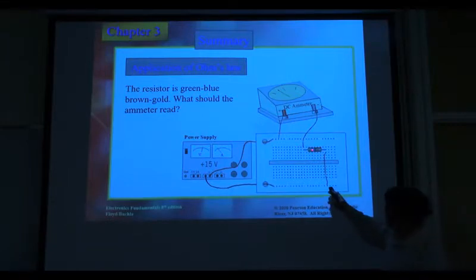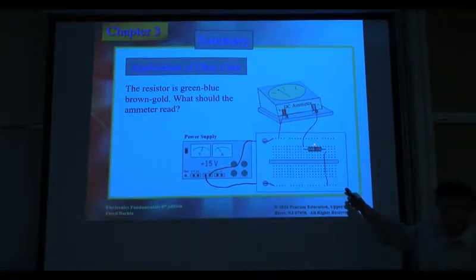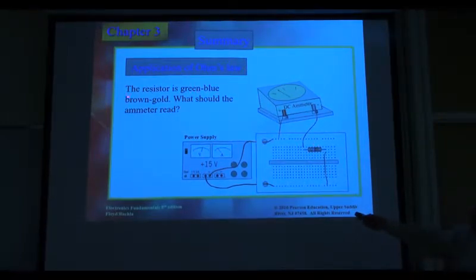Okay, now we know this resistance, right? What is it? It is green, blue, brown, and gold. Gold means plus or minus 5%. This one is green, what is green? 5, right? This one? 6. This one? 1. So this is 5, 6, 0, so 560. And this one is only the tolerance. What is the number here? That's what we are looking for.